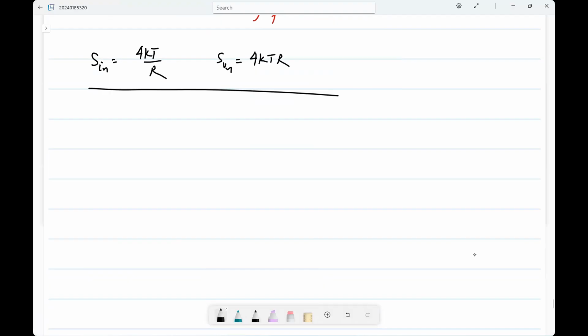I mean, I don't know whether we will definitely encounter that. Actually, the previous one just said that it is independent of the resistor value. Now I'll go and ask how will we reduce the noise there? Because as a designer, that's what you want to do, right? You design everything, it is working functionally. Only thing is the noise is higher. So now you want to realize the same function with lesser noise. What will you do? Reduce temperature. Yeah, very good.